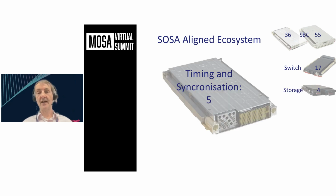And there are a number of timing and synchronization cards. So going back to the diagram, the simplified diagram I had of a SIGINT EW type system, the real key is that all of the elements of that system that are doing the signal processing need to be very accurately synchronized in time. And that's typically done through a GNSS connection. They come in on one of the RF connectors you can see on the bottom left of the picture on the screen.